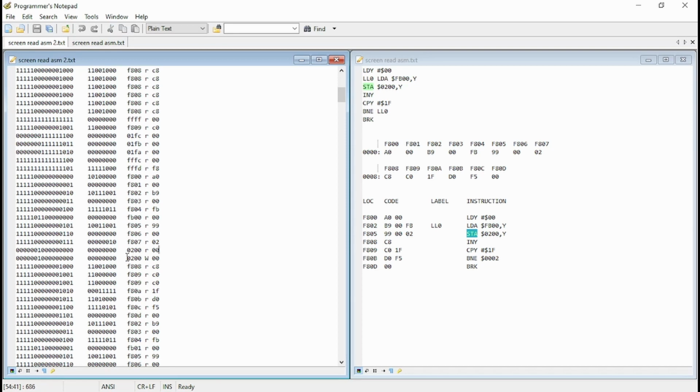So it does that read, then it writes 00 to the ROM. Now remember, it's not writing to anything, so if we wanted to read it back, we obviously wouldn't be able to read any data. But it's quite happy trying to write out to something that it can't write out to. So we've done that. Then we're F808, which is increment Y, which is the C8 opcode.